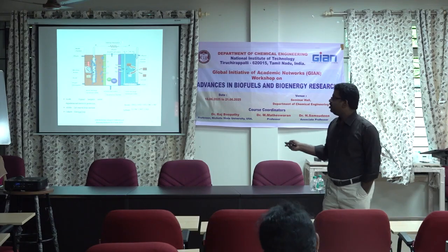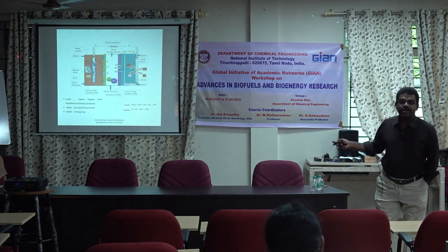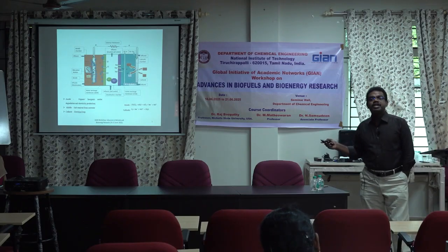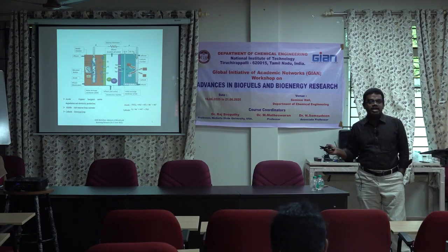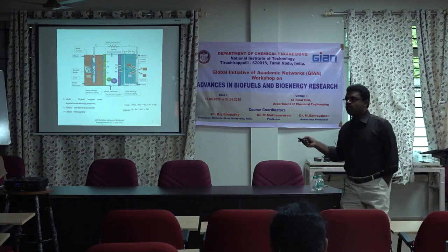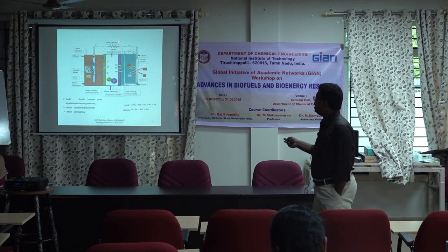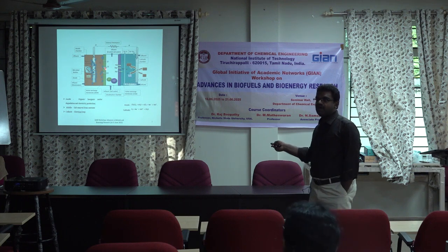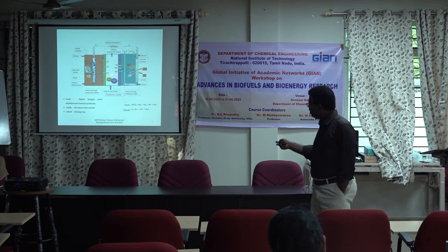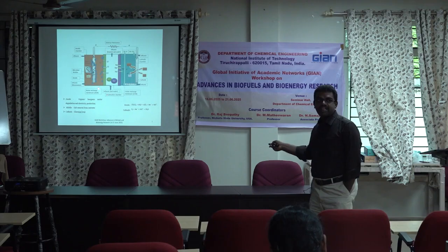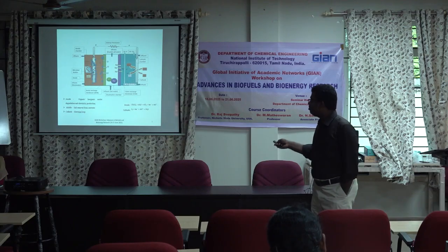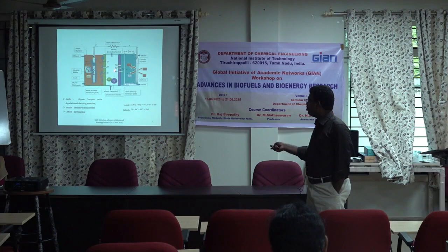Here the desalination chamber contains salt water. Salt means it is a NaCl solution, that is, sodium chloride. There will be a concentration difference between these two chambers because of the driving force. Here we have the anion exchange membrane, which transfers negative ions, so whatever anion is there will transfer. If there is any positive ion, a cation, it will be transferred to the other side.